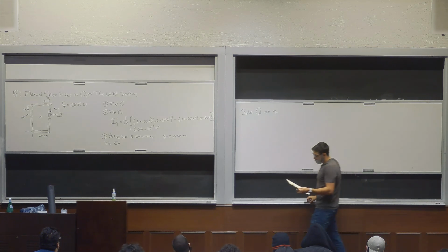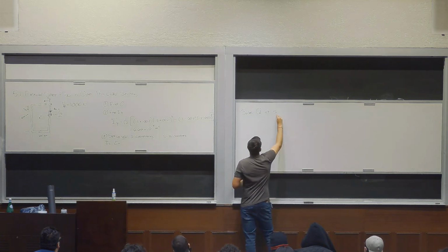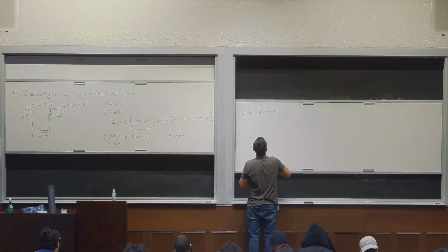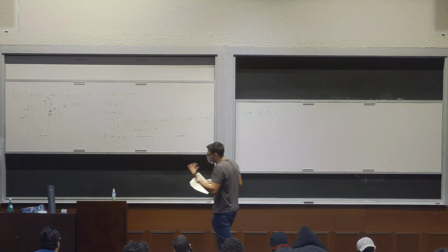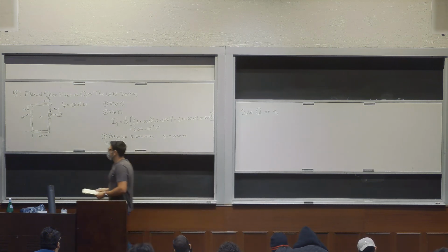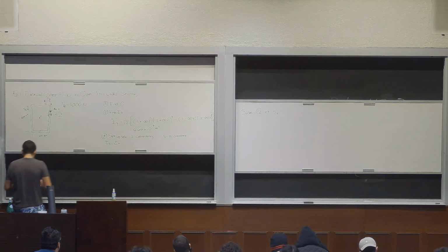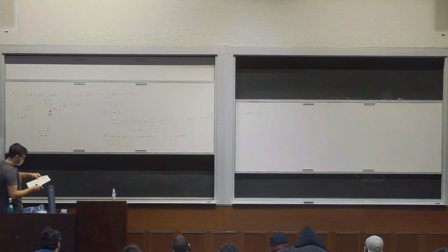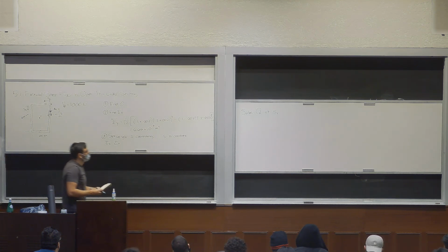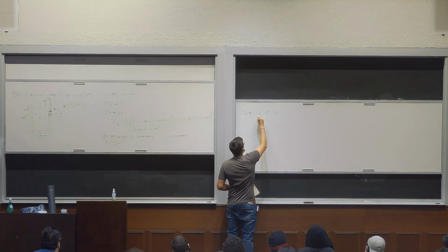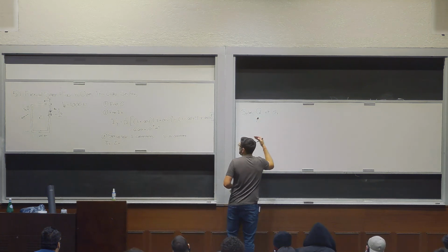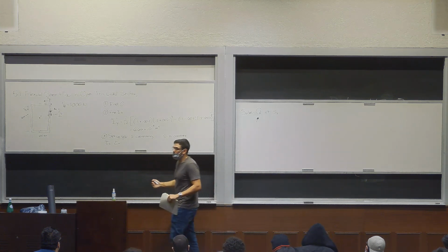So we're going to solve now for Q at S2. The key here is that this big Q, this first moment of area, you're going to be progressively adding as you move along the whole contour.